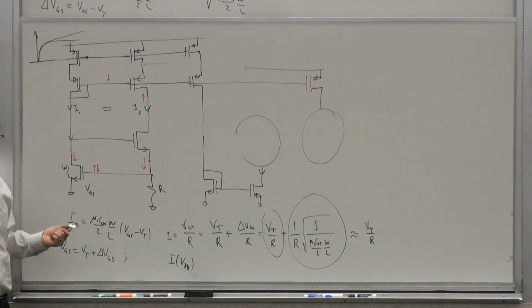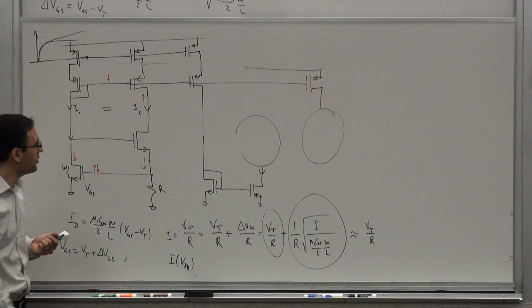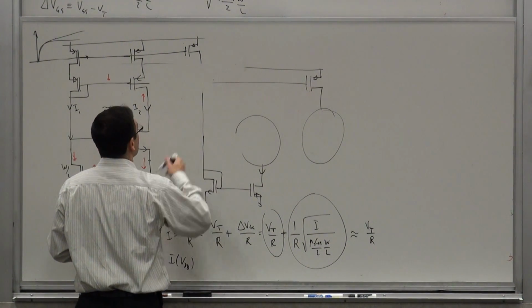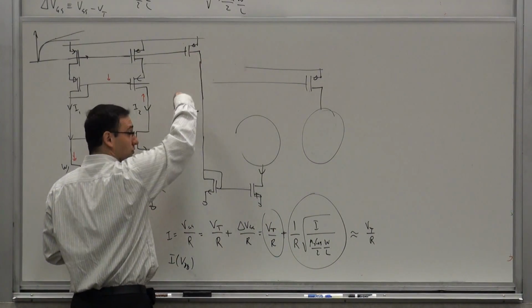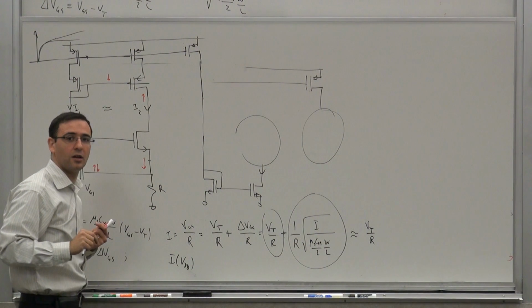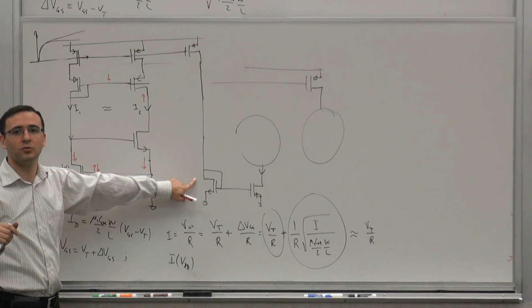Okay? Yes? Suppose you did a Cascode, when you're mirroring it, you can still use a single PFET for mirroring at the top, right? Oh yeah, you could do that. You don't need this, for instance. That gives you more headroom, but a lower output resistance. So depending on what you're going to be doing with this, you may or may not want to do that.